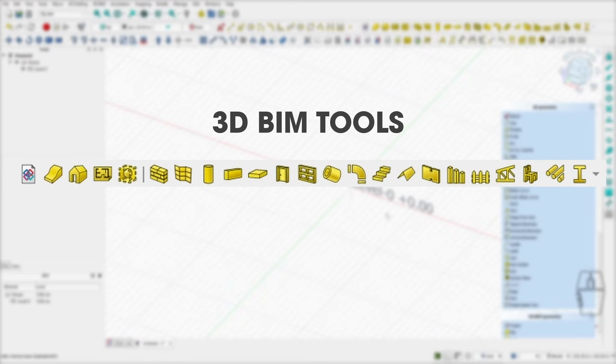Next on our list, the 3D BIM tools. These tools are specifically designed for architectural elements, allowing you to create a wide range of building components such as walls, slabs, stairs, roofs, and doors. They also enable you to convert objects created in other workbenches by assigning the appropriate IFC class. Some tools require preliminary sketches.